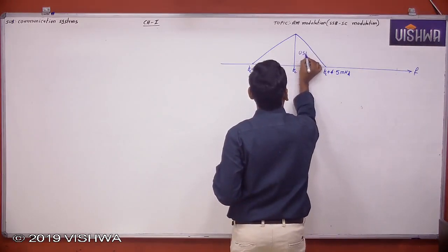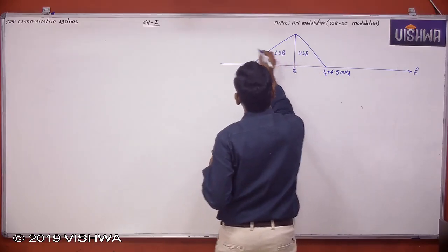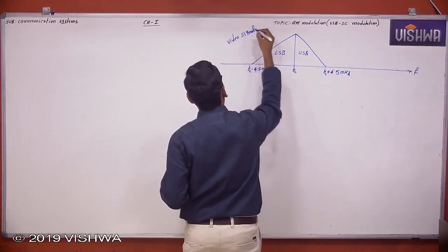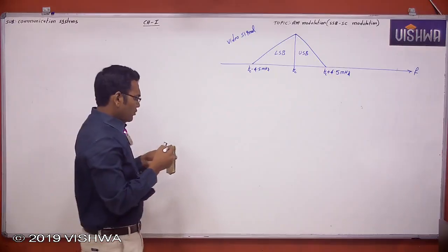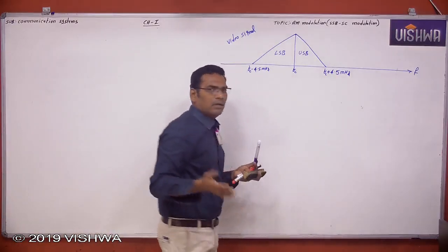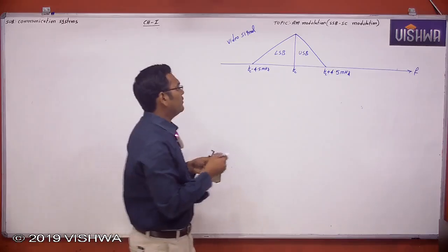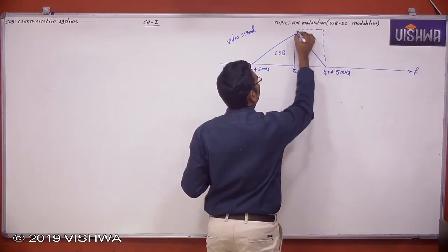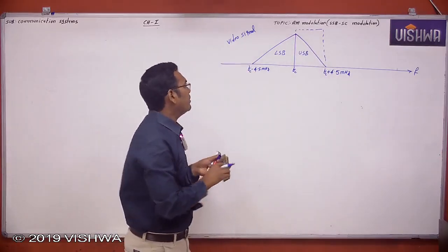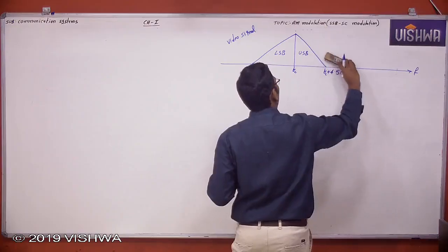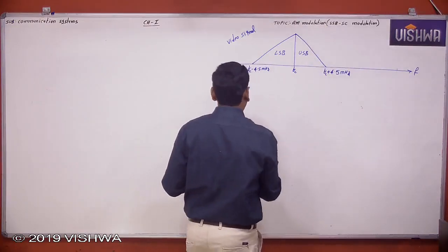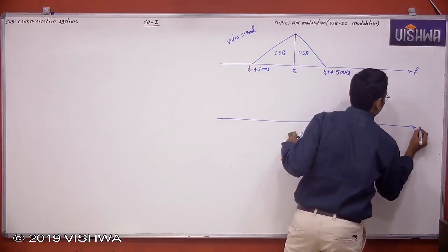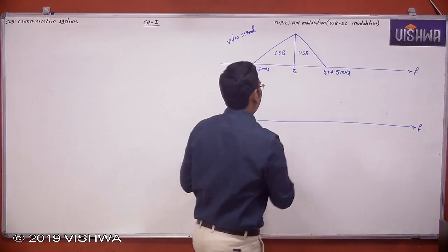Now let us take, this is the upper sideband, this is the lower sideband of the video signal after modulation. Right? Now I want to take one sideband completely, but it is not possible by using a practical filter. It is possible by using an ideal filter. If you take an ideal filter, it is cut exactly here. Okay, but no ideal filters are available. You have to take care. You have to design only a practical filter, such that you design a practical filter like this.